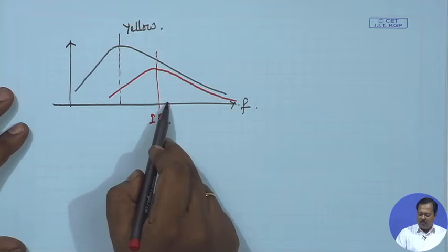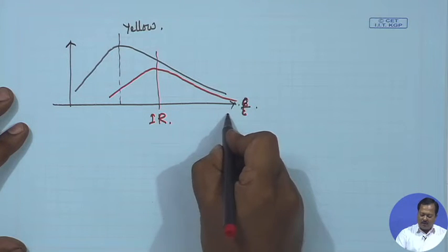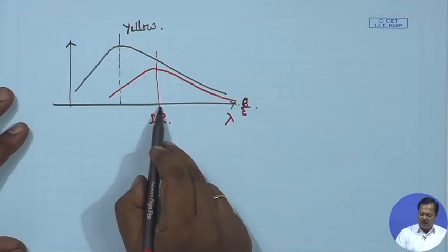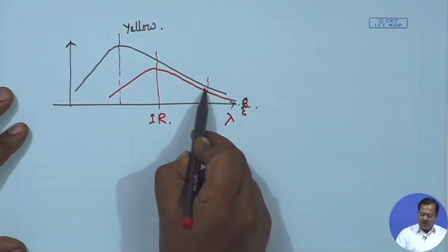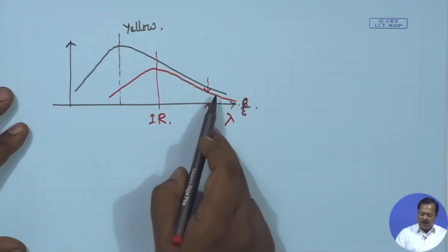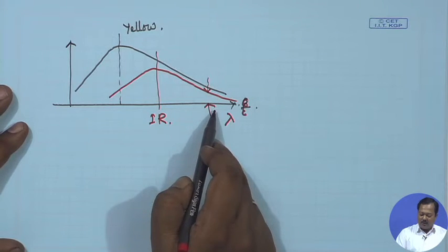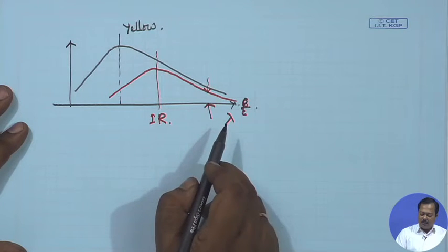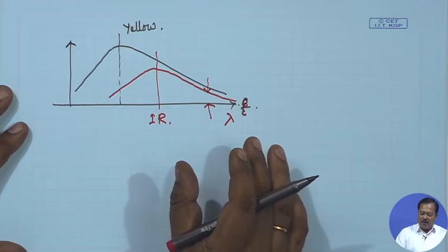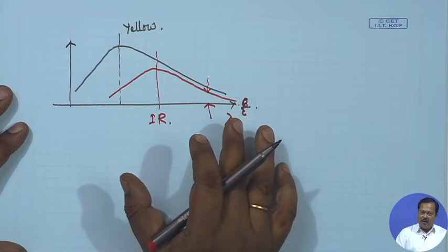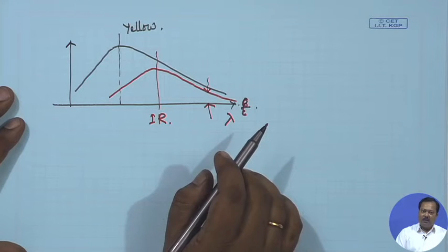And if we go further down, sorry, this is not versus frequency, this is versus wavelength. So, if we go further down, that means if we decrease the frequency further, this spectral component decreases, but it is not negligibly small at millimeter wave frequencies. Now, if we have any antenna, let us say it is focusing towards earth from satellite, then it will collect this radiation which is coming out from earth's surface, and we have a degrading effect on the antenna performance.